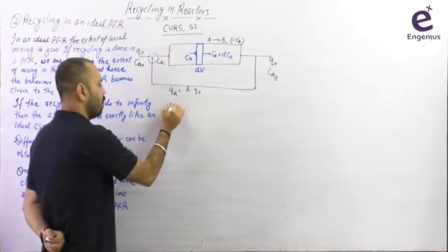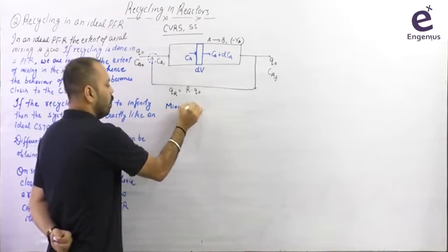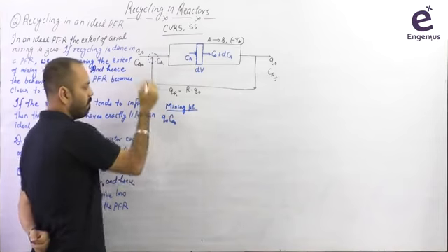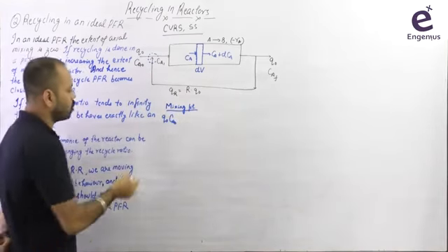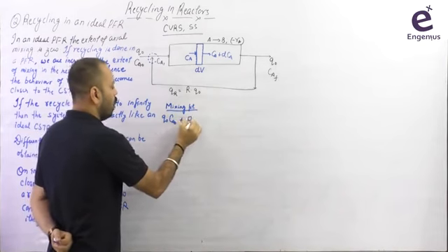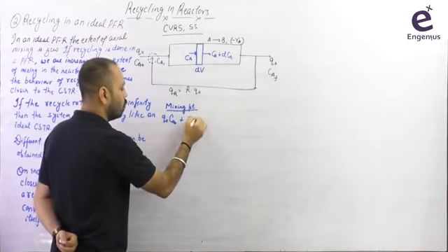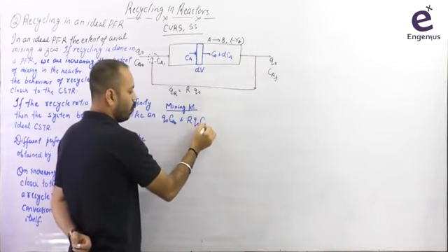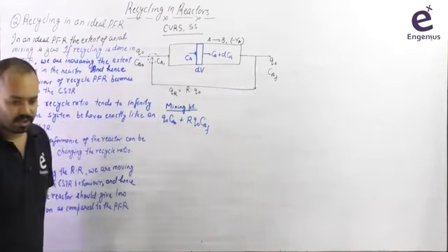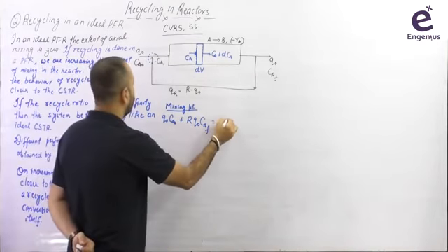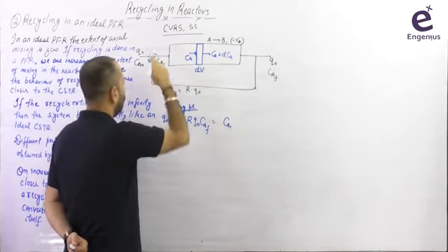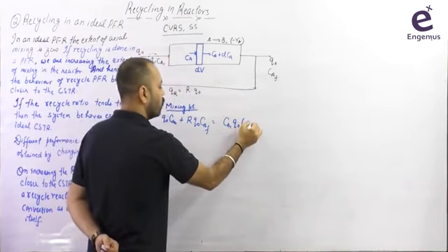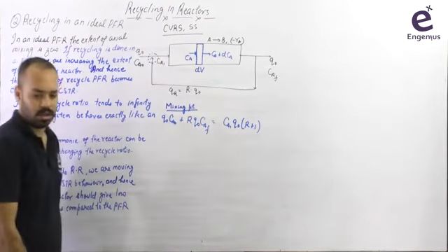Let us first write the balance here at the mixing point, the balance on A. What is coming? Q naught into Ca naught. From the left hand side, what is coming from the recycle stream? That is plus R into Q naught. I told you that all these concentrations remain the same because this is a simple splitting point, is equal to Ca1 multiplied by Q naught plus RQ naught. So that is Q naught into R plus 1. I hope all these things are clear to you.